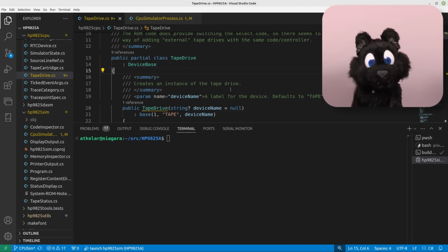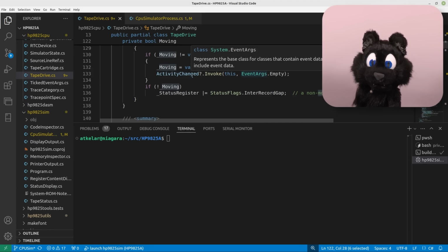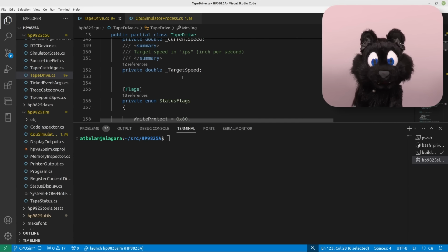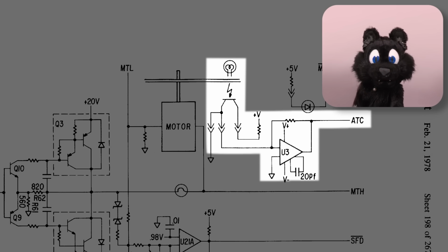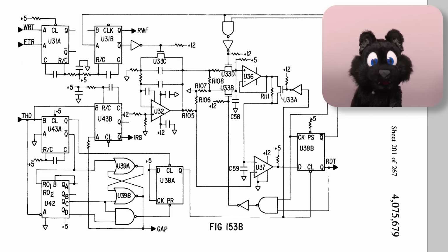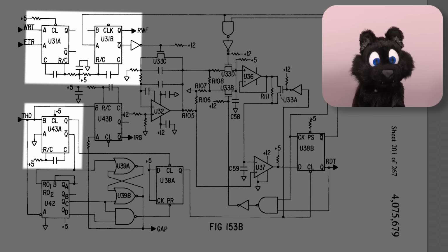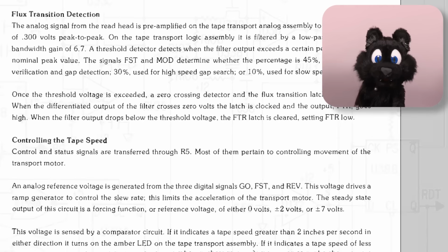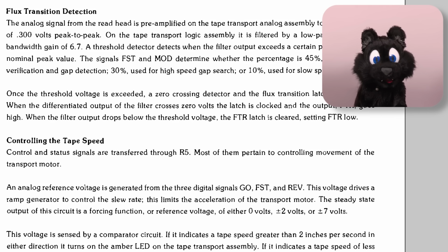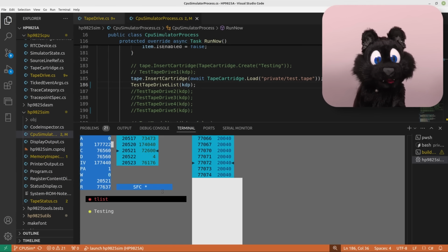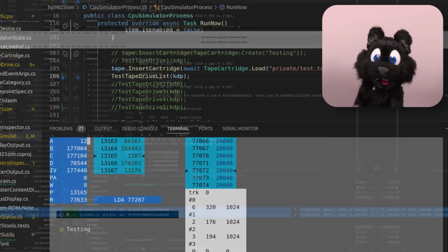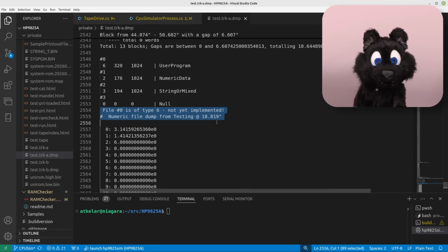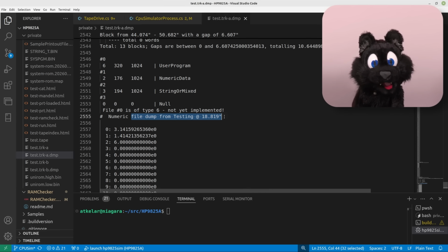The last bit that I'm currently still working on is the tape drive. And boy, that is a tough nut to crack. Some control signals around it derive from the tape movement sensor, the tachometer, and some are purely time-based. Between the HP patent and the service manual, I got pretty far along and can already rewind a blank tape, mark files on the tape, read and write files on the tape. That is to say, I'm almost done already. What's missing is the DMA integrated search feature and a way to actually modify the tape images.